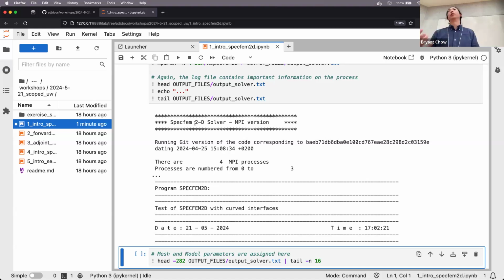There's a trade-off essentially of stability within your simulation. If you have a very finely discretized mesh, so you have really small elements because you want, say, high frequencies, you're going to need a much smaller time step in order to keep the simulation stable. And the log files will give you suggestions on what the best values to use are.